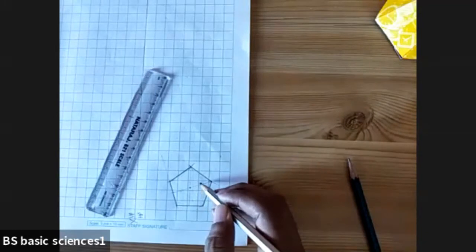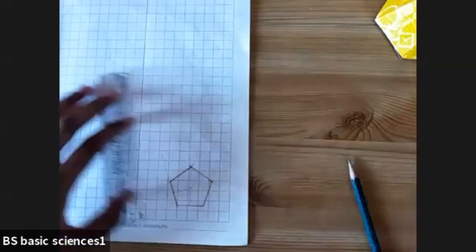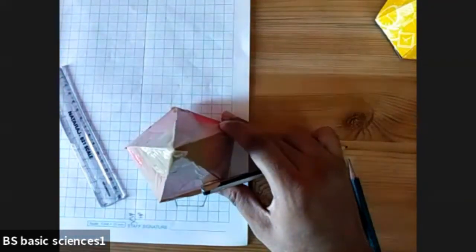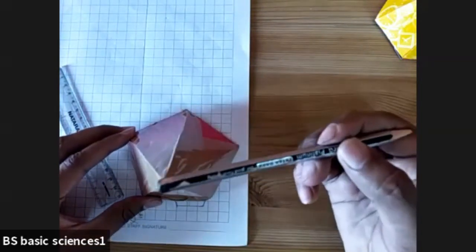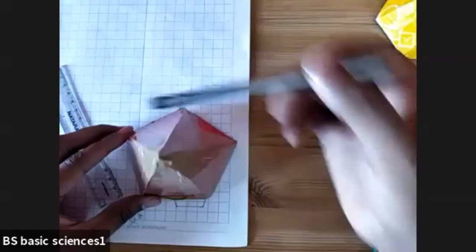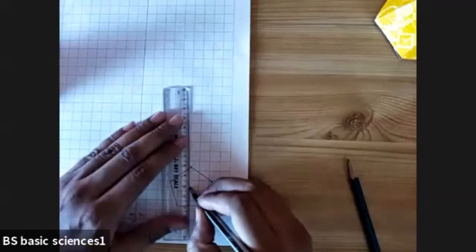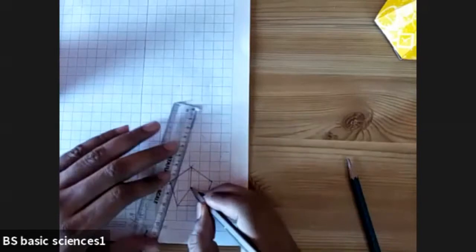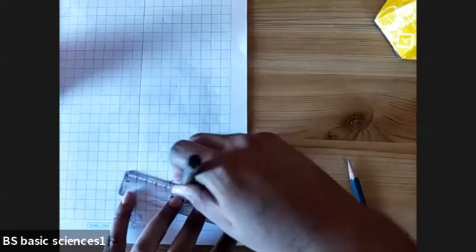Now you know how to find the midpoint of a pentagon. Then how will the pentagon pyramid look in the top view? Listen, when you look from the top of a pyramid, you can see the 5 slant edges: 1, 2, 3, 4, 5. The 5 slant edges run from the midpoint to all the corners. They are visible, which is why they will be drawn thick.